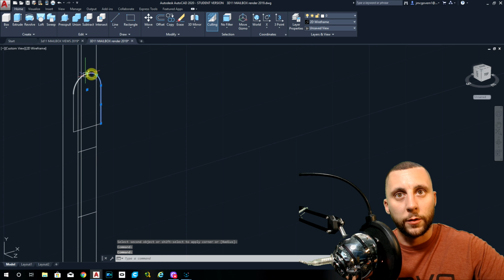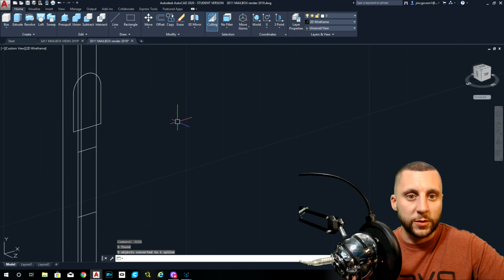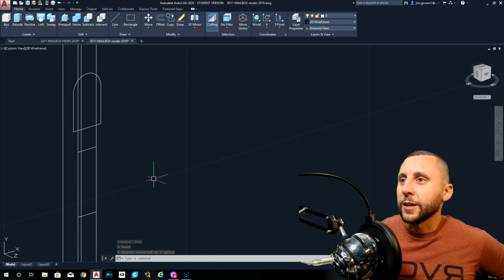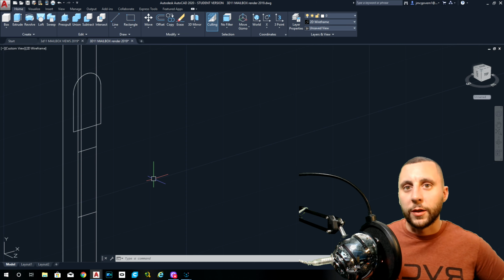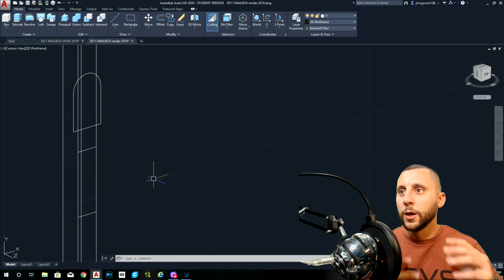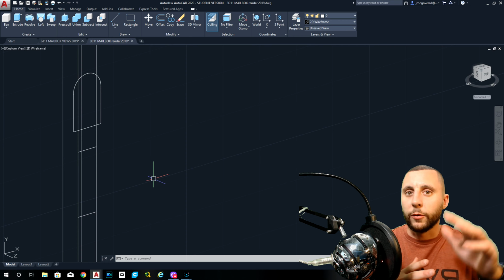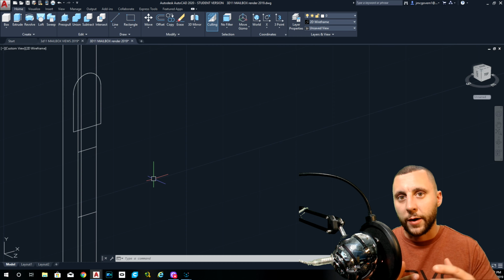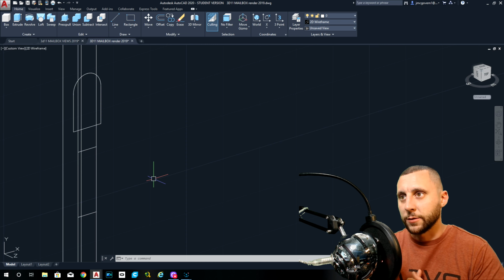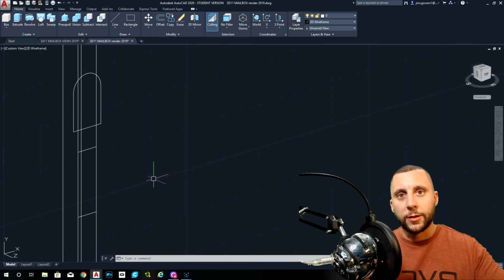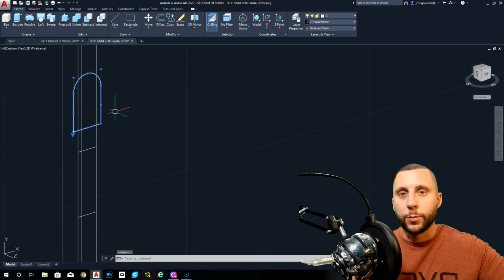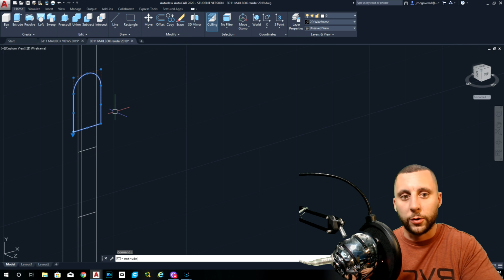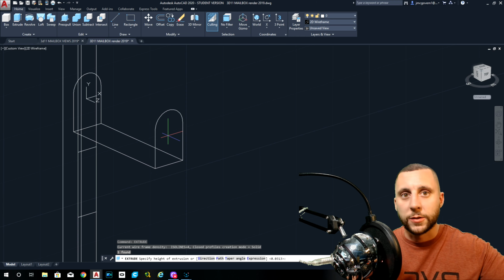Now take 1, 2, 3, 4, 5 and join those together. It should say 5:1. I'm getting a spline, which is kind of strange, but I think it's actually because of my file. I've already drawn many things in this file, and right now I'm trying to draw something 2D, but since I've drawn something 3D so many different times in this file, it won't recognize something as a flat plane anymore, and you'll get a spline. This should still work, but for you guys, you'll probably see that you'll actually get a polygon, or a polyline, I should say.